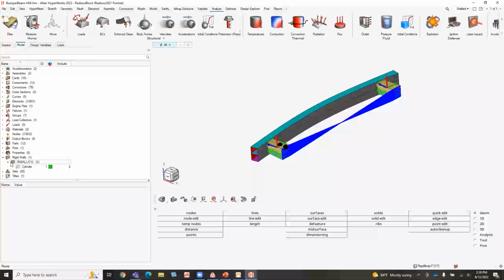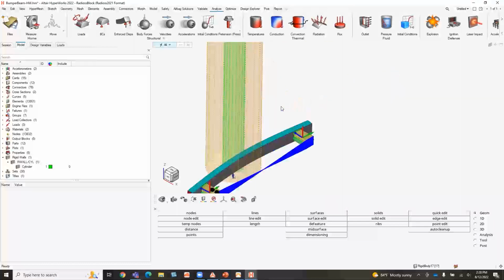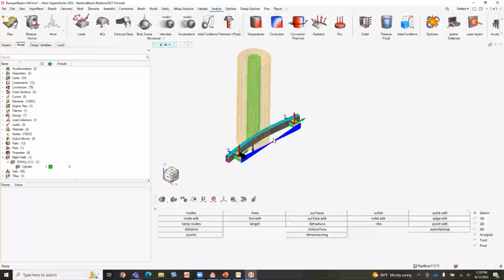One of the things you'll see here is we specified that rigid wall, which is pretty cool. We can look at individual parts and specify rigidity. And this is exactly what we'd be running in an explicit study, looking at impacts. So we have this cylinder we just modeled, and I'm specifying that as fully rigid.